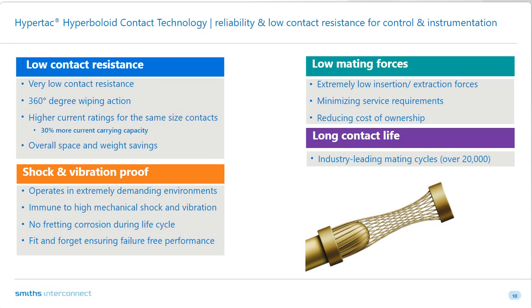The third thing is the higher current carrying capacity. Remember I was talking about smaller being better for a connector in an environment like this. That is attributed to the contact technology that we have designed, because typically our design is able to carry 30% more current in comparison to similar power ratings from other connectors, which ultimately leads to overall space and weight savings, which are crucial requirements in an industry like this.